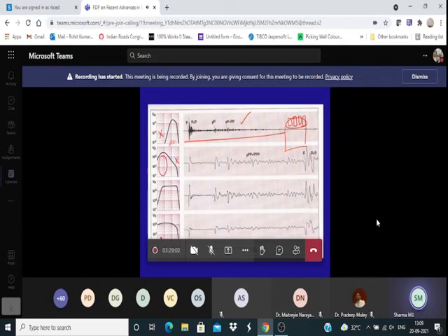I mean 10 to the power -1 or -2, 0.00. So all the lower frequencies are recorded here. Here in this case, it is a broadband. It has recorded the higher ones also and the lower ones also. And here you will see that the lower frequency is also there and the higher frequency is also there. In this case, it has all recorded the lower ones but not the higher ones. So the seismogram looks like this.